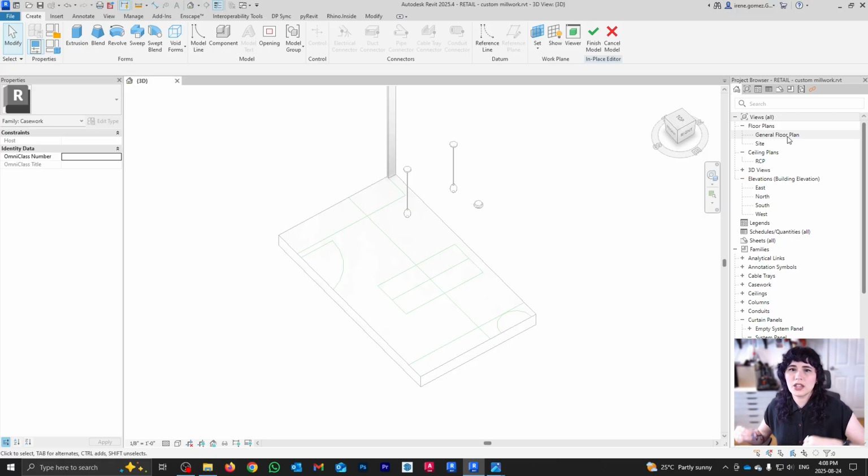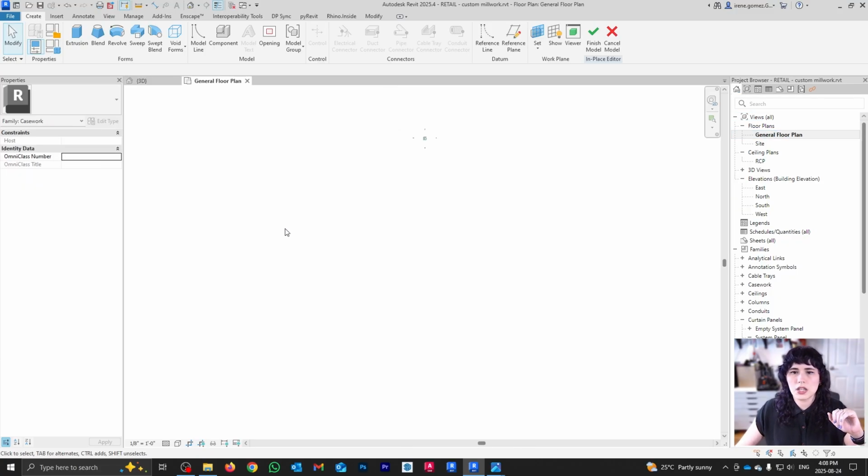If you're working with something that is, let's say, wall mounted, then maybe the ideal work plane to start from is the wall that the thing is mounted on. Because if you think about it, that is the plane that is defining the main position of your millwork. So don't just assume that your starting point should always be the floor. Sometimes it's easier to start from the ceiling, to start from the walls, okay? But in this case, I'm going to go with the floor plan.